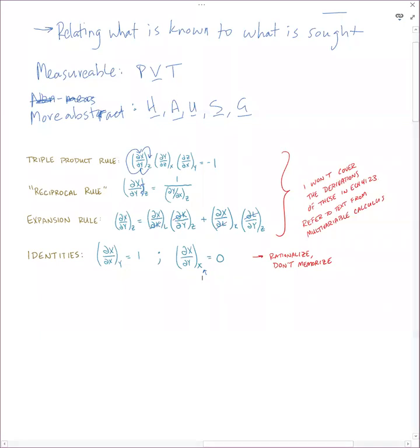So just summarizing what we derived last time, remember we had a Joule-Thomson valve, and we wanted to relate the change in temperature upon an isenthalpic expansion of gas. We said that dT was equal to the partial of T with respect to P at constant H times dP. And through a series of steps in the derivation, we got this reduced to, remember, we don't necessarily know what T as a function of P and enthalpy is.